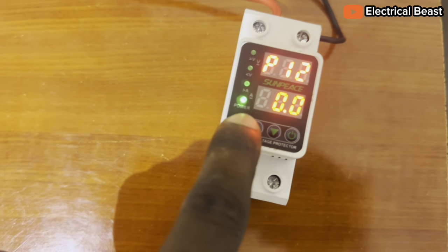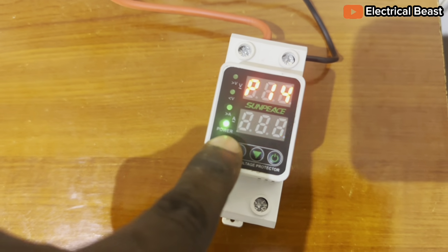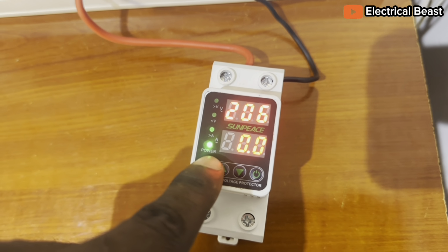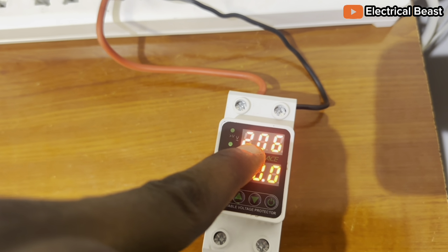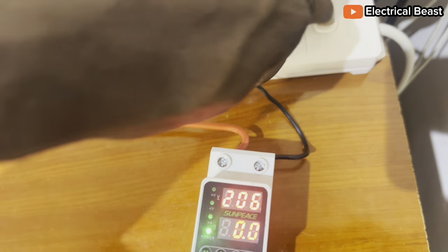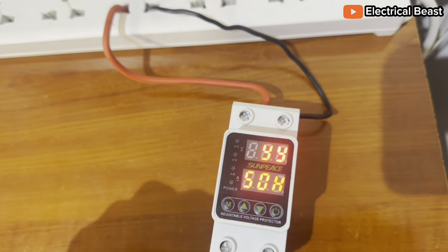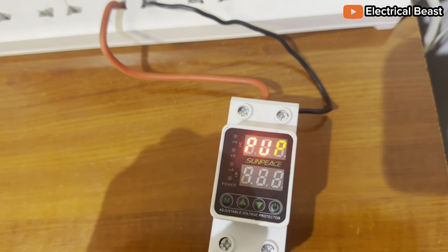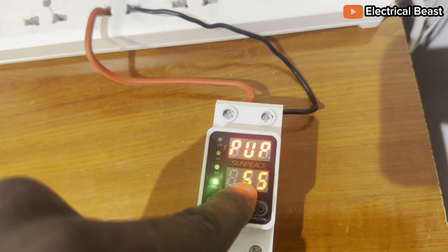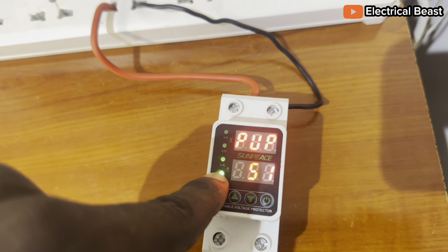So which other program do we need to set? I think the rest is not actually needed. So we have our voltage protector working on active. Right now the value is 206 volts. So when I switch it on and off, it's not going to come on immediately until 60 seconds, 1 minute. It's going to count down from 60 down to 1.